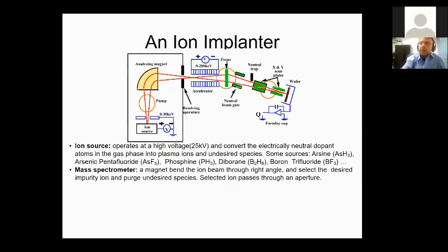Okay, now how do we do the ion implantation in the first place? We need an ion source. To create an ion source, we have a filament. That filament will provide the electrons, and then there's going to be a gas available for us here. That gas, let's call it AB, a gas of AB, will be ionized by colliding with these electrons, and then we will create the ions that we want. The ions that we produce will be guided in a very clever way thanks to these magnets, because charged particles can be guided with the external magnetic force. We'll cover that in a bit.